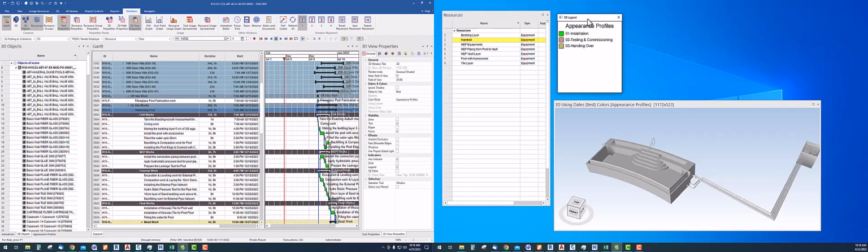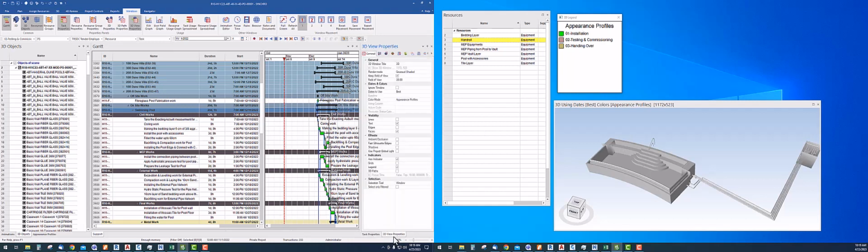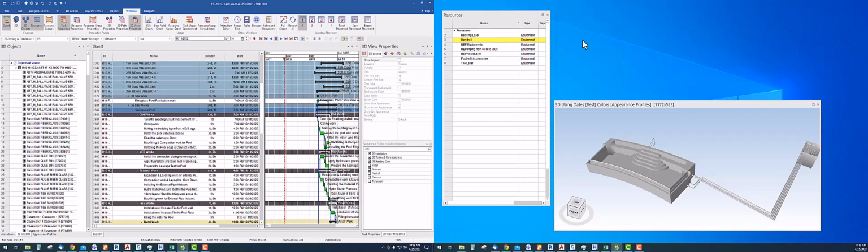So where can I control this from? I guess from 3D view properties I can control this, whether I want to see the 3D legend or not. So if it is task properties and you are not able to see, how to control this, you go to 3D view properties. And here you will see legend, show legend. If I turn it off, my legend is turned off. If I turn it on, my legends are turned on.